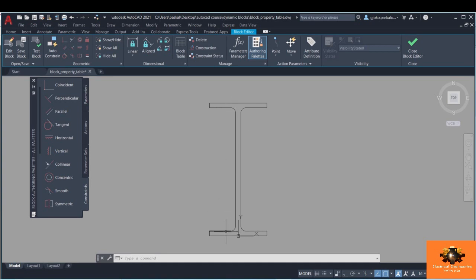You can see all of these lines should be connected to each other no matter what, and that's why we need the geometrical constraints. So when we change the dimension of the beam, everything will follow and go as smooth as possible. And for that I'm going to show you a little trick that I actually talked about before. We are going to use this auto constraint option and assign all of the geometrical constraints.